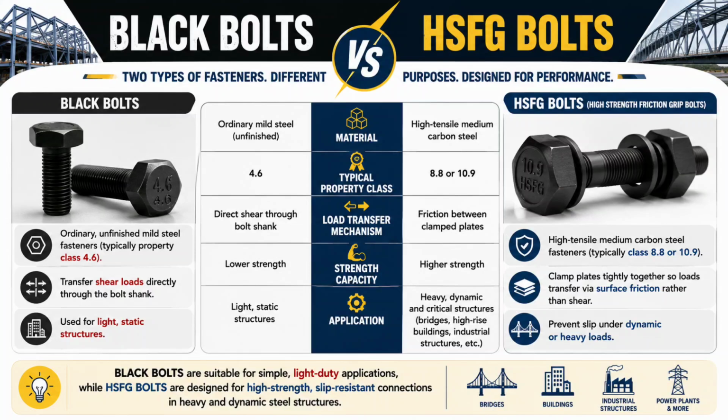Coming to HSFG bolts. HSFG bolts are high tensile medium carbon steel fasteners, typically of class 8.8 or 10.9 grade. In HSFG bolts, the load transfer mechanism is through surface friction rather than shear. These types of bolts prevent slip under dynamic or heavy loads.